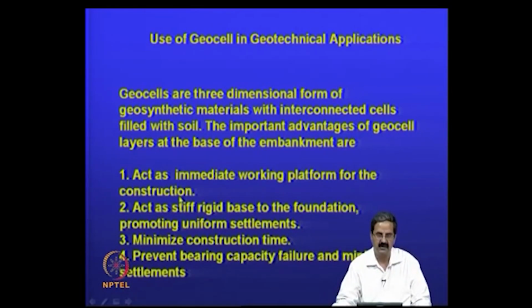for the construction. Say, for example, if you want to have a working platform and the soil is very soft, one can spread this geocell material and then start filling up soils. Actually, you can put a geotextile at the bottom, put a geocell, fill up all of those things, and put a roller, then use it as a platform.